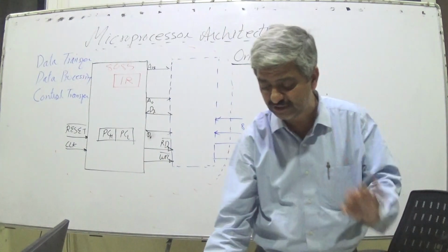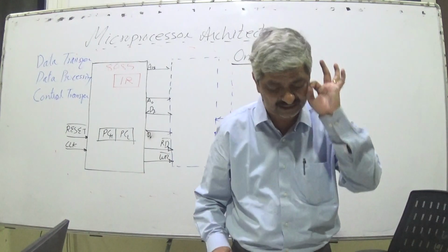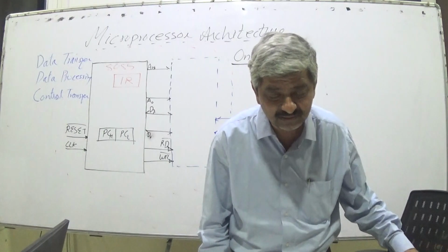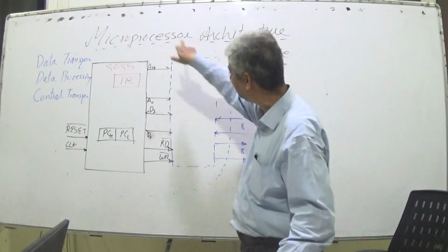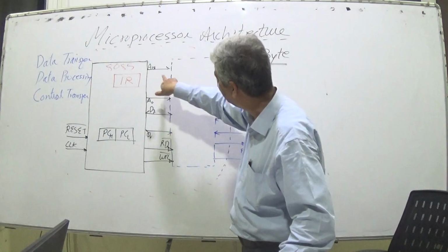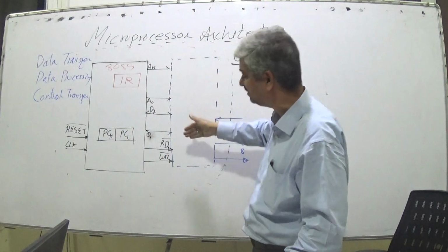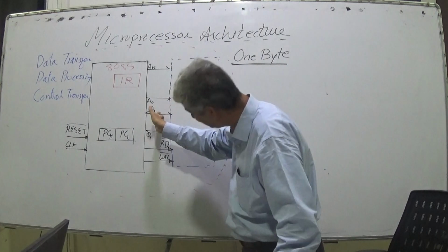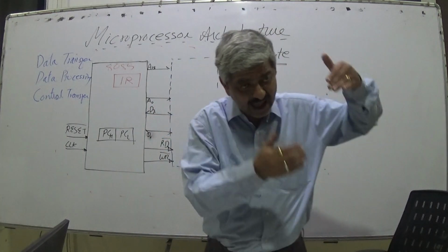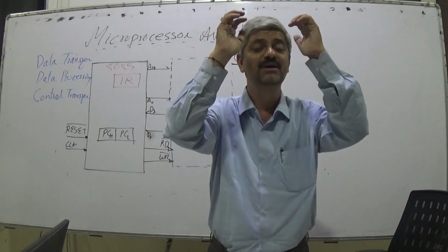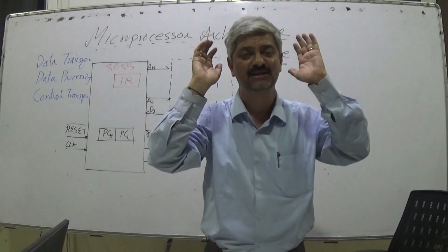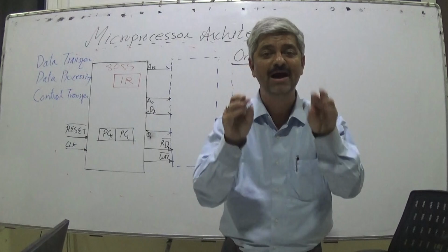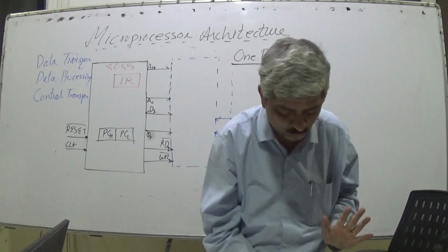The microprocessor outputs 0000 on the address lines and activates read bar. It is expected that, with the arrangement of a proper decoder, one of the multiple memory locations will put something on the data bus. So as a result of the first read cycle after reset, the microprocessor receives one 8-bit value.